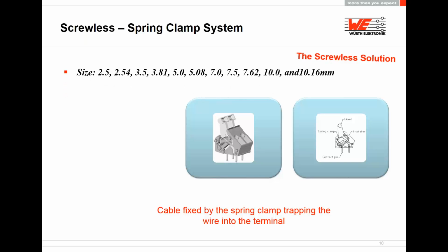Pitches from 2.54 up to 10.16 millimeter. Wire gauge up to 10. Rated current up to 30 amps. And number of positions, that's an amazing number of positions, just in case you have multiple screwless applications within your product, it can go up to 24 positions.